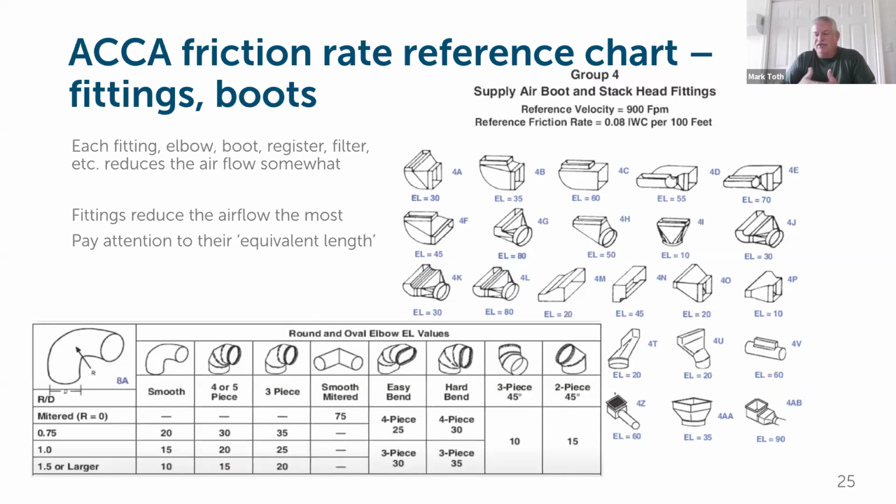So the fans in your units have to be powerful enough to move the air through the duct system that you're designing. Because you may be picking a unit that's 100 CFM, and by the time your duct system is done, that unit might only move 50 CFM of air through that duct system because it doesn't have the power to overcome all the fittings you use.